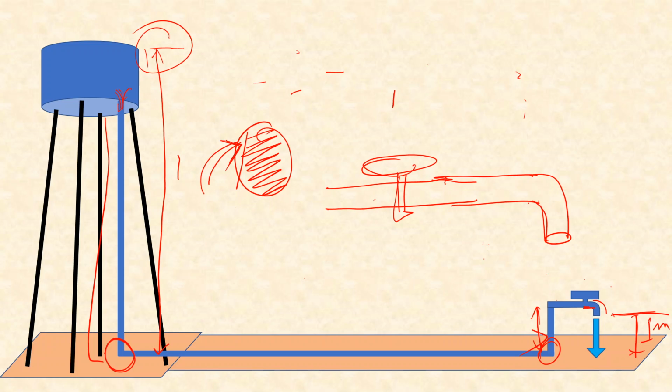So in that case, once you have only let water flow through this portion and through this entire cross section flow is blocked, then what will happen is, just like by blocking using your thumb, velocity through this portion will be very high. And that's why in some cheap plastic taps, suppose, you see that when you close the tap halfway, the water will not flow smoothly and it will flow either through one side or making 2 or 3 streams and so on.